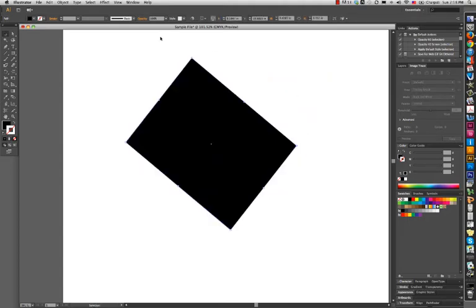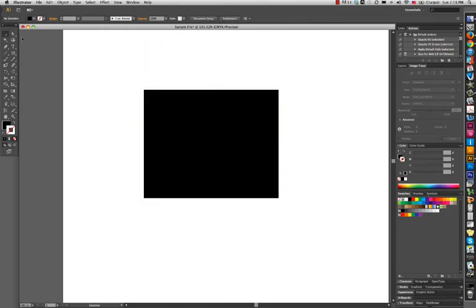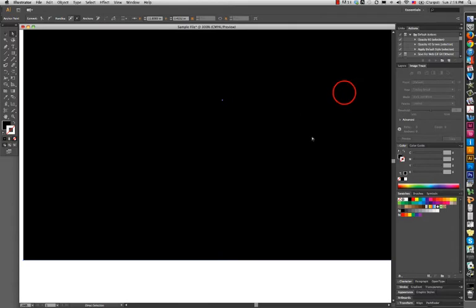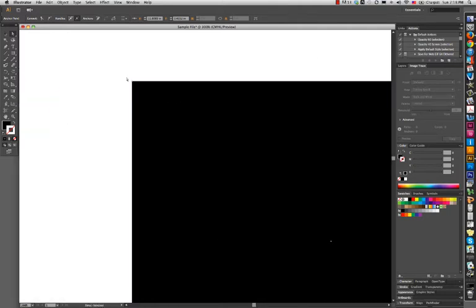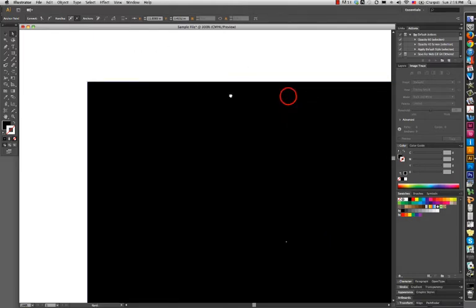depending on how you're using some of the prompts that come up with the different arrows. If I choose the other selection tool, the direct selection tool, this lets me work with one part of an object at one time. So instead of clicking on an object and getting the whole thing, if I zoom in here, you can see a little bit that I now have a blue filled-in square at the corner of the object, but the other corners have a blue outline with a white fill.